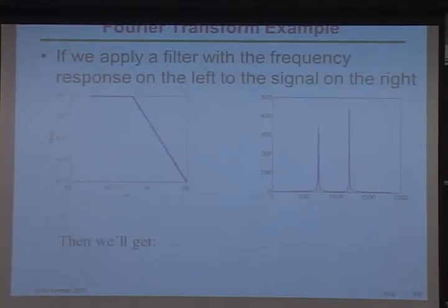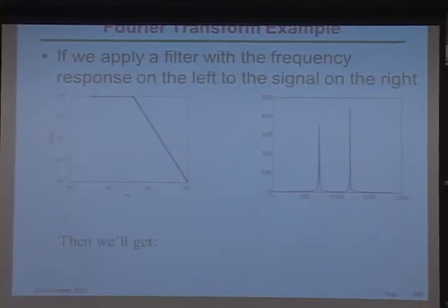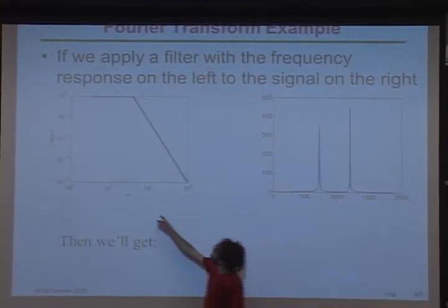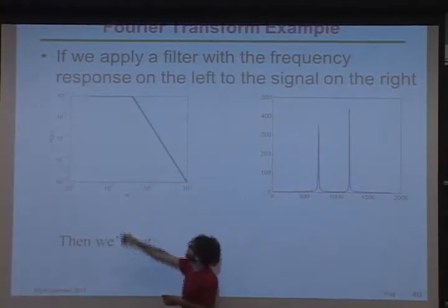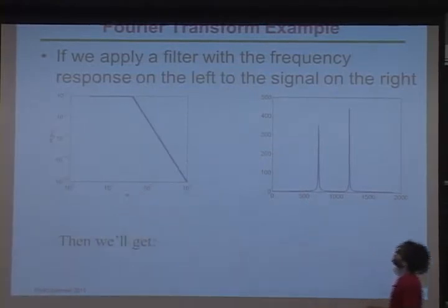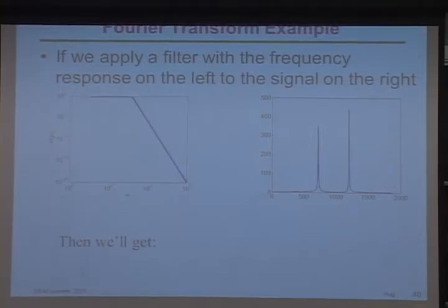So what's cool about filtering is if we take a filter, for example this one right here, and the cutoff frequency is around 1,000, and it's really steep. As soon as I go a little over, we're dropping like 10 orders of magnitude. What we'll see here, and actually it's 7. So it's a 7th order filter because you're dropping off with the power of 7 of the frequency.